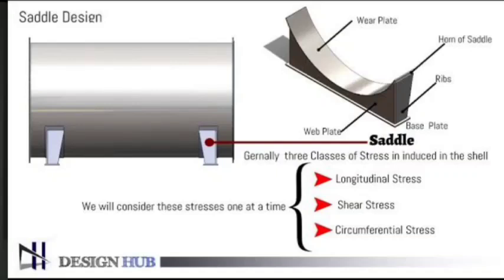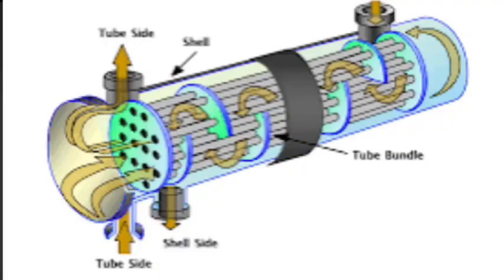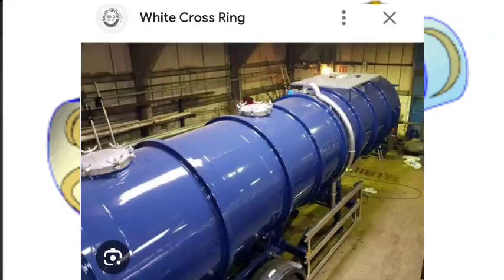Okay. Because there was a case wherein I was designing a heat exchanger, and I was facing the same problem, and we did not want to opt for the stiffening ring, because that stiffening ring has a separate set of stresses of its own. Correct.